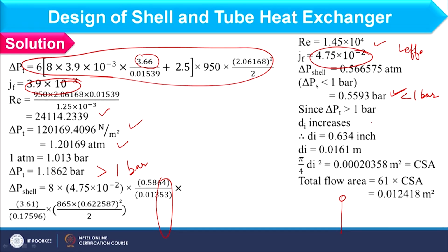But when you reduce tube passes, you should also consider that in velocity, and in that case velocity will be reduced. So here instead of changing the passes, we will change another parameter, and that is the di of the tube, and that must be increased, right.